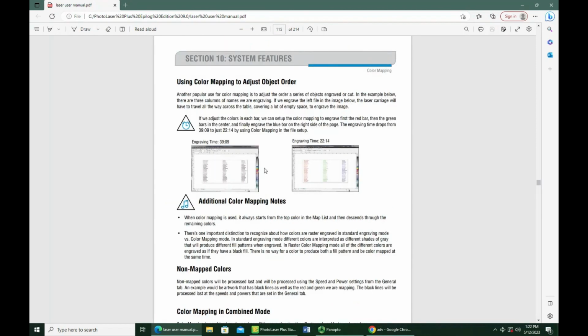There is a third way we can send things to the printer. We can break them into chunks by color, and the color will just tell them to print that entire color before another color. It has nothing to do with the color that the part is going to be. So in this case, instead of the printer running across this entire row and then down across the entire row, it's going to instead do all the red, so it's going to have a very short travel, and then it's going to do all the green, and then all of the blue. So I could have turned this vertical, and it would have done a similar thing, but I can have it set up horizontally and break items into colors.